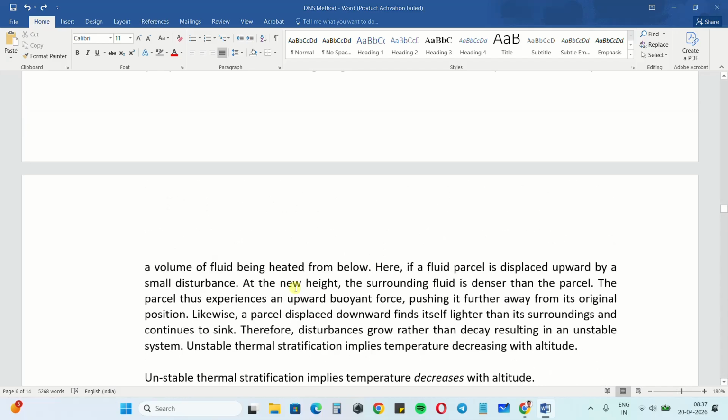So in our case, we are considering stable stratification because, as we saw, stable stratification suppresses this motion and reduces the chance of buoyancy driven turbulent mixing. So that's a kind of worst case situation for the heat exchanger exhaust. The exhaust gases stay around the heat exchanger stack without getting easily dispersed into the free stream. That's why we are considering stable stratification in our simulation, in order to study a possible worst case scenario.